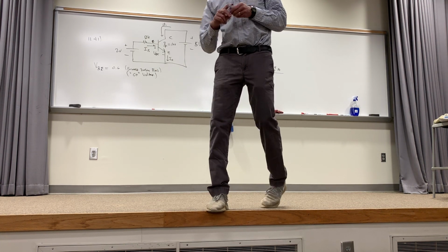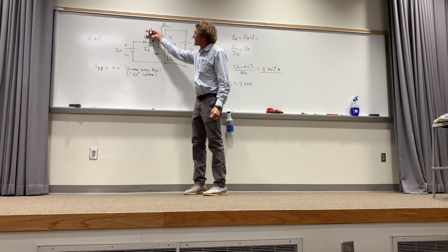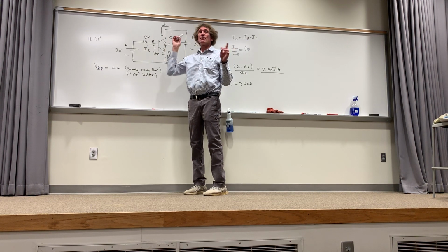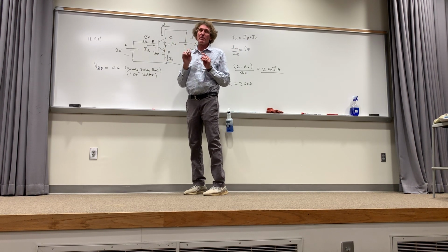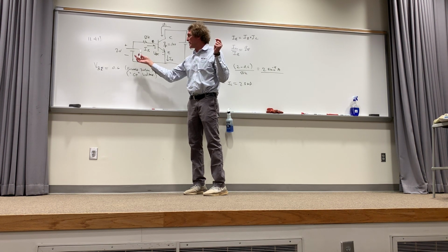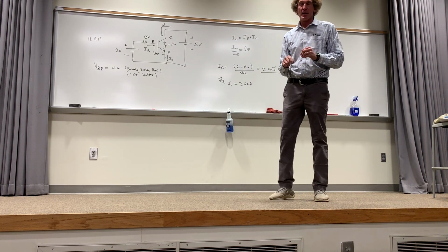But I have to be careful about this, because if it was self-biasing and I pulled the resistor down here to here without having that, then that voltage does play a bit of a role. But it's only the base current ultimately that matters. Does everybody understand that? Only the current through the base. This is called a current-controlled current amplifier.